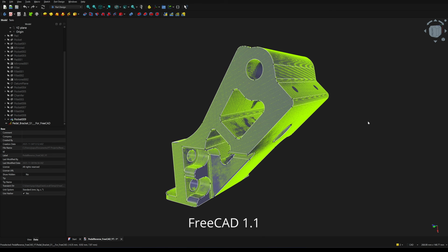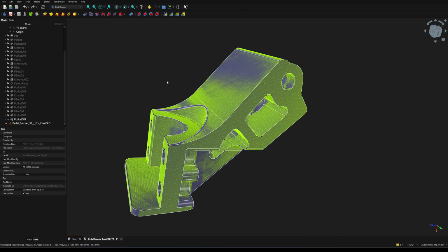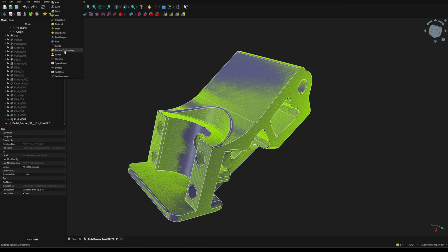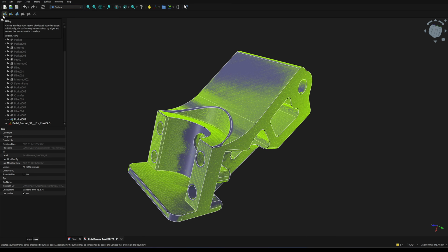This is FreeCAD version 1.1. It can import and work directly with point clouds, but when it comes to mechanical parts, it doesn't support creating 3D lines, arcs, or splines. That makes surface modeling pretty tough, and converting surfaces into solid is still buggy, so I avoid using it for very complex surfaces. Another reason I don't use it much is that larger point clouds slow down the viewport, and the 2D sketching tools are still buggy and slow to work with.